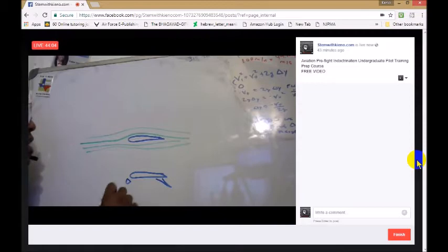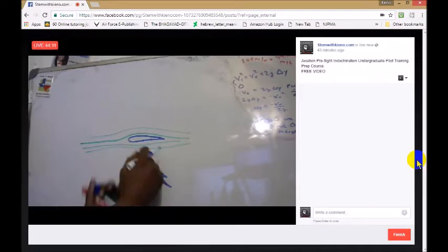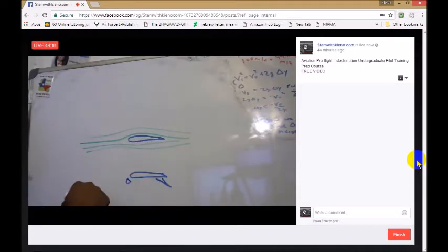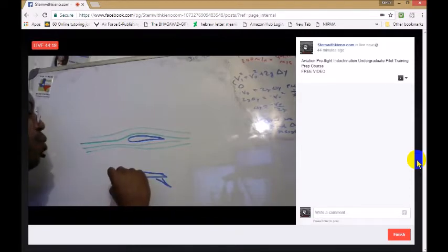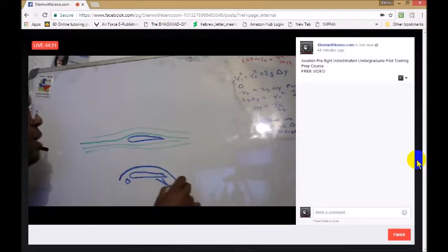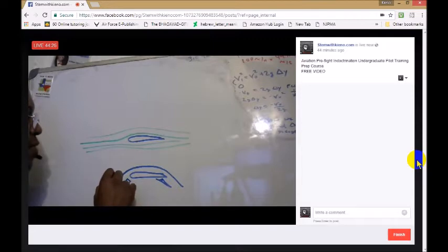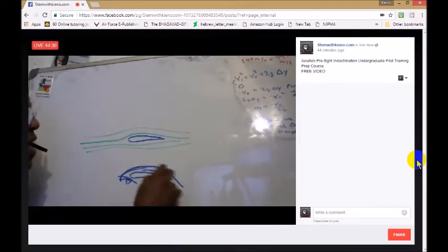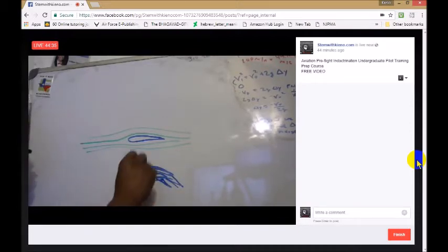Now, if you look at this wing and this wing, when the flaps and slats are retracted, they come back into the main body of the airfoil, whereas in this situation they extend outside. So what we have is more camber, or curvature. If we have a slotted airfoil, then we have more airflow paths being created, and it's speeding up the airflow, and we're generating more lift in this situation.